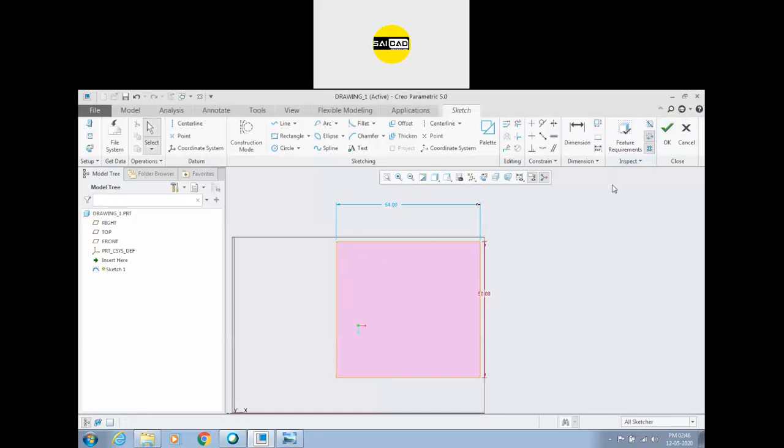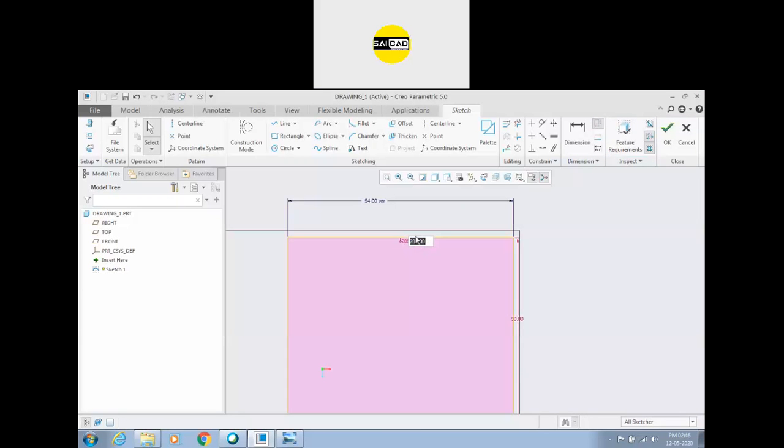Okay, you have to select all the sides. Again, select the parameter, select all the edges of the object. Basically, that will define the loop. After that, select OK. Then select the dimension to be driven. So I want this driven dimension. Now you can see this is a variable dimension and we have the parameter of 208.